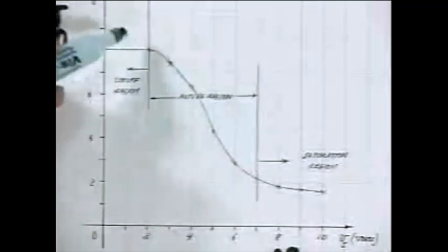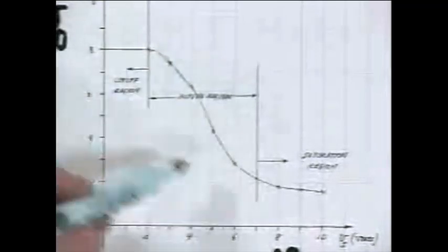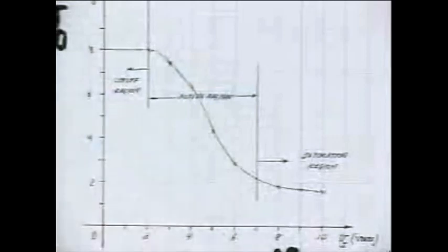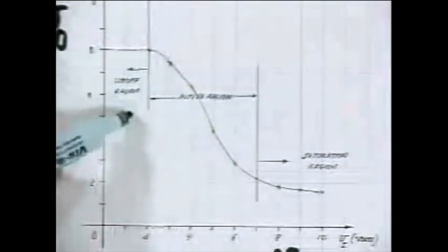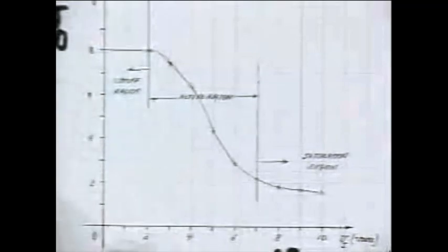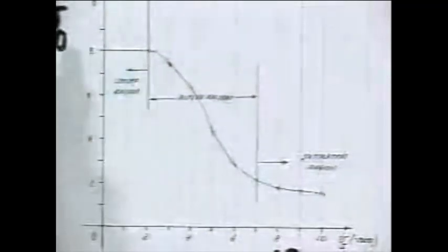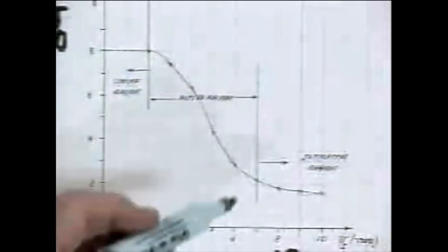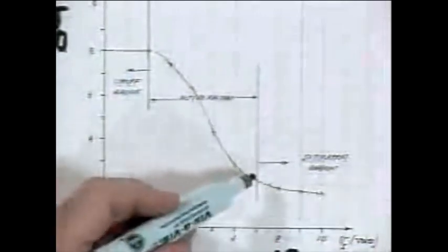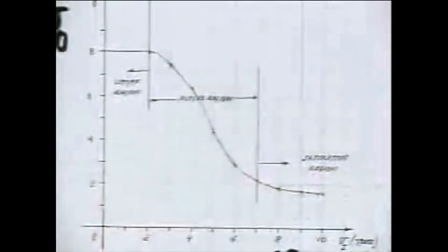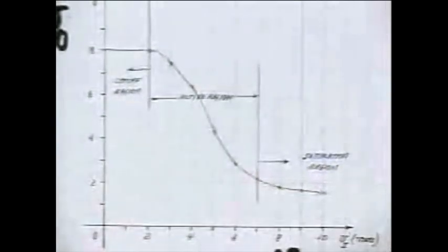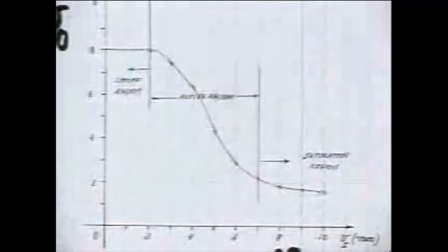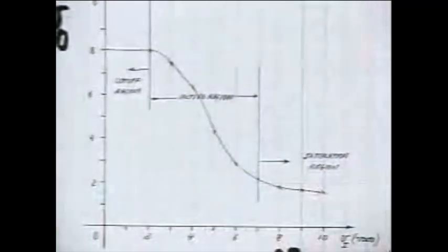And for this circuit, with this device, this is the active region, where there is a strong dependence of output on input. I've referred to this as the cutoff region because for V sub I less than 2 volts, indeed the transistor is cut off. In switch terms, it is in the off state, and so there's no dependence of the output voltage on the input voltage. And then as we go to higher and higher input voltages, this curve kind of tails off with not much slope, and I've referred to that as the saturation region. That is, the output voltage is saturating at some level in the range of a volt or 2.